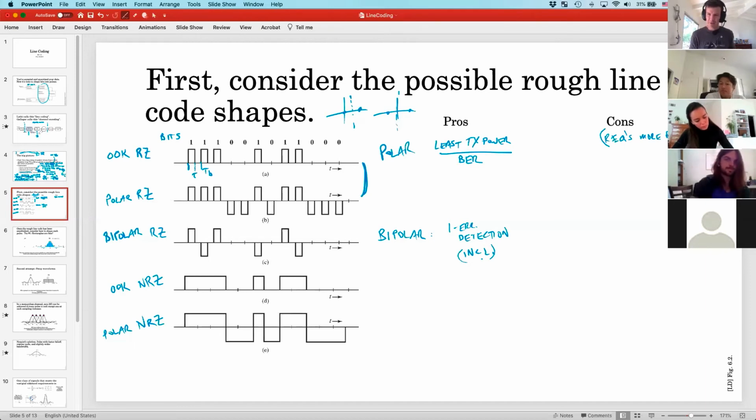Can you see why that would be? If you're sitting at the receiver, you're either going to get, say, a 1 or a 0 or a -1. If you get a bunch of zeros in a row, okay, could be right, could be wrong. If you get a 1 followed by the next non-zero thing was another 1, one of those ones has to be wrong. Okay, so you can't know which one was wrong, so you can't correct, but you can raise a flag and say, oh, excuse me, can you send that again? Retransmit request is what that's called. Okay.